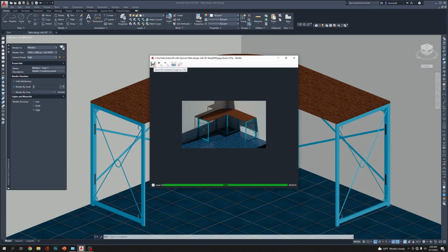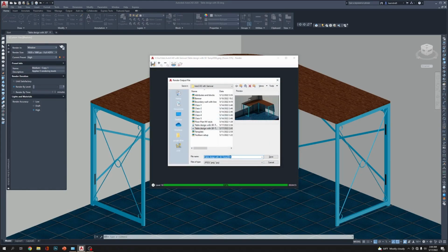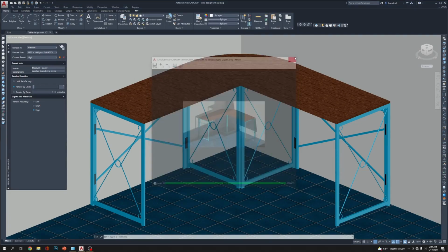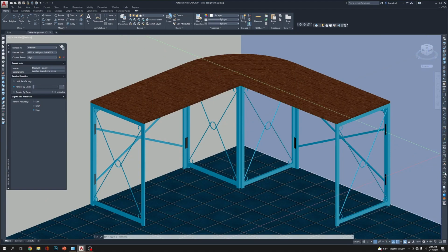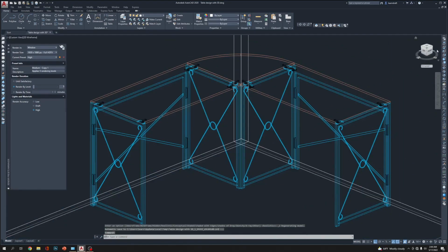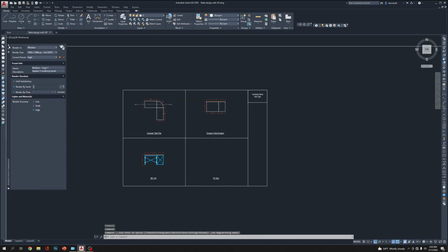This is the floppy disk, you can see this is for save. I'm going to click here, and I have just saved the rendered photo, so I'm just going to click cancel. You can click on this button and save it accordingly. This probably comes as a PNG. Just change it to JPEG so you can use it anywhere. So I'm going to click cancel here and go to the 2D wireframe, go to the top and close the